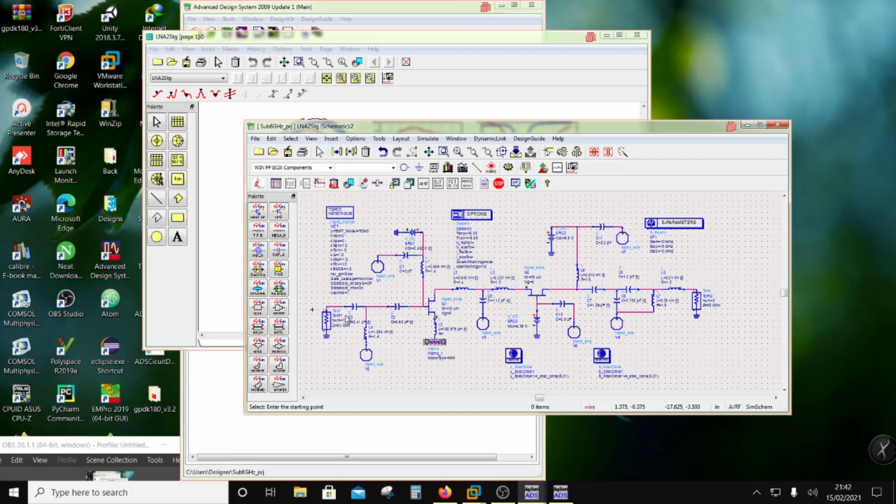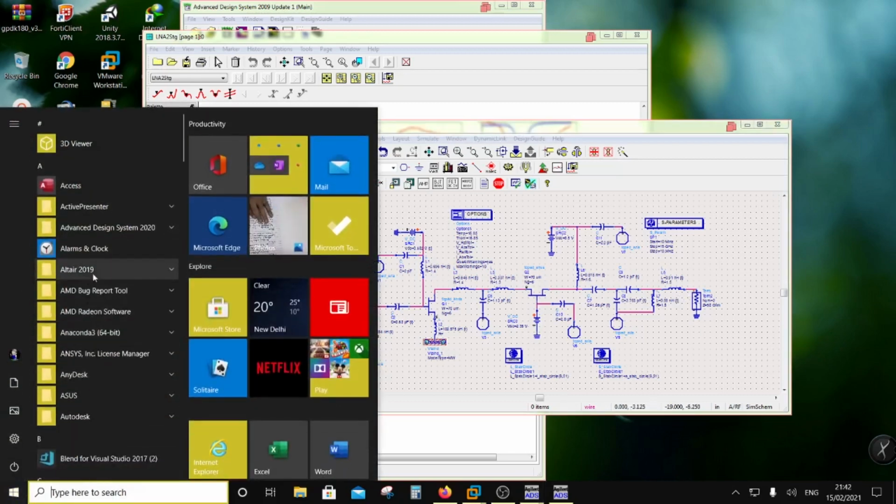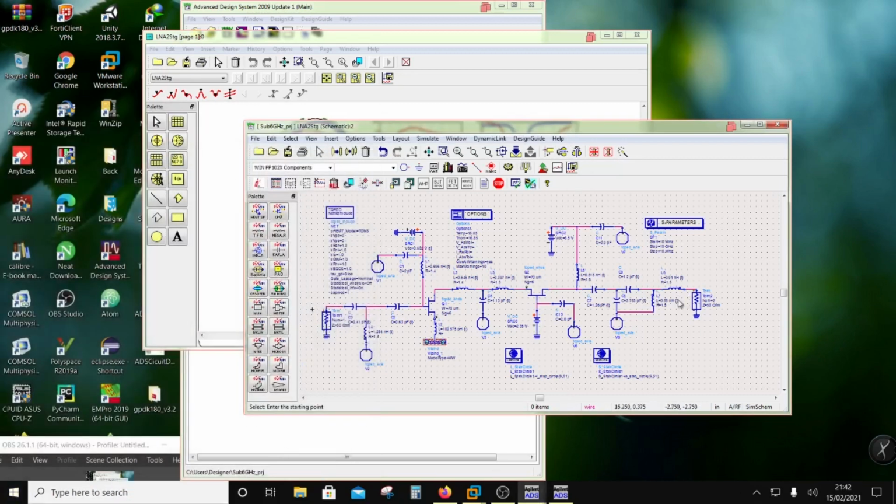Now, this LNA is part of a radio front end chip. The output of the LNA is going to see bond wires, while the input of the LNA is going to see a switch, right? The switch is not yet designed. So when we transform this layout, I would first have to put bond wires at the output. Two wires of 1 mil are going to be sufficient to put out the power, right?